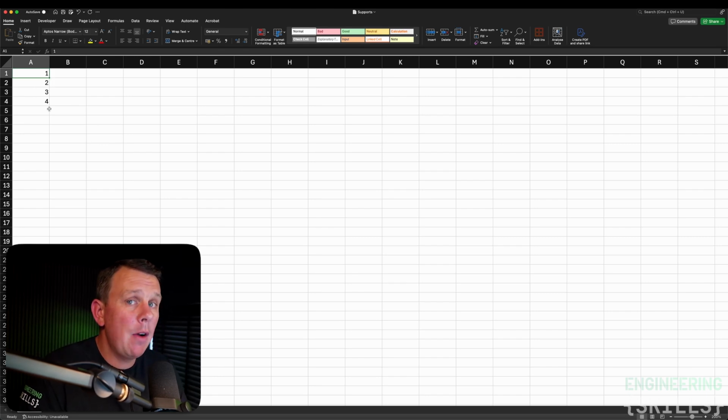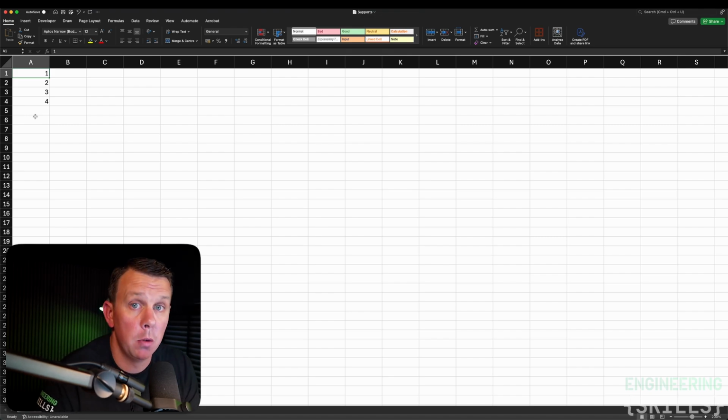So we now have all of the data that we need. We have the nodal coordinates, we have the member definitions, and we have a list of restrained nodes. This is enough information for us to take over into our Jupyter Notebook and start building an OpenSeesPy model for this structure that we can then analyze and evaluate. So we'll jump over to our Jupyter Notebook next.